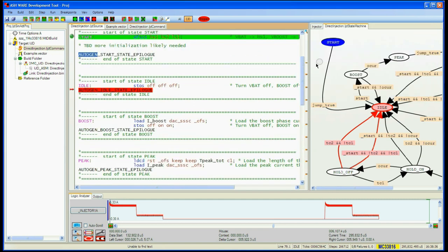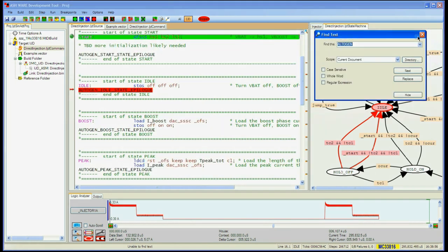Let's close the search dialog. Notice that the search markers remain. What happened to the debug markers, current program counter, breakpoints, and such? At the top of the markers pane is a little magnifying glass. Clicking on it toggles the markers pane between search results and debug results. Double-clicking on it reopens the search dialog. Let's close it back down.